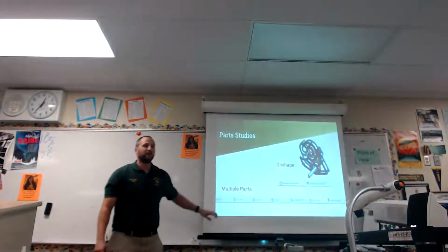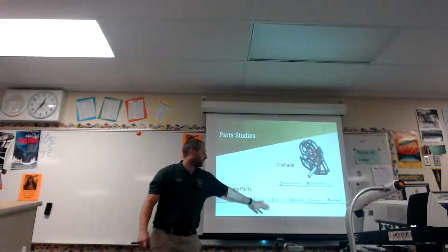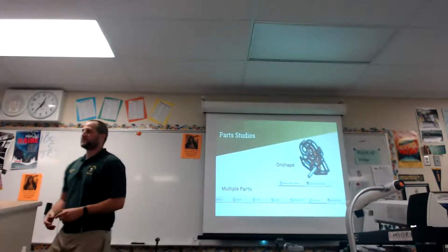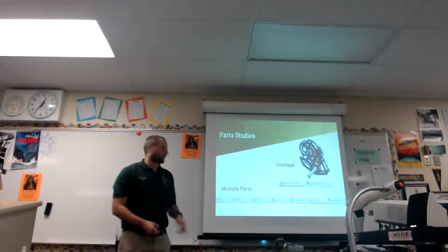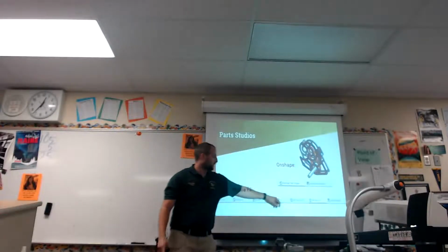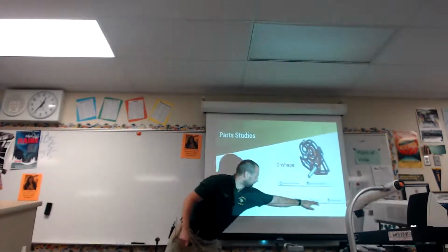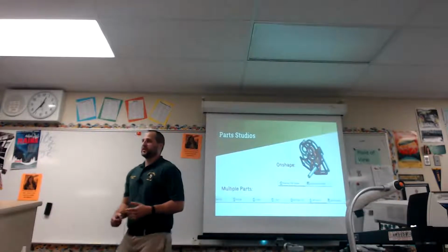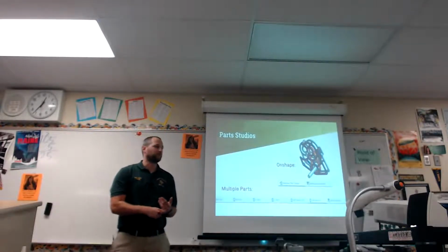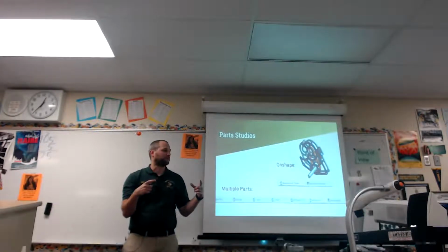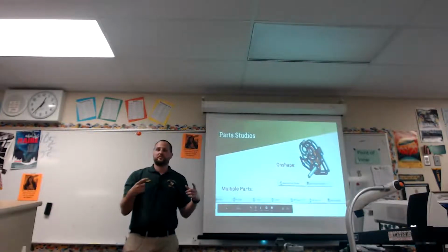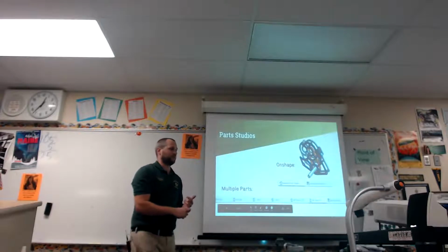All right. So one of the things that's unique or cool about Onshape is along the bottom, you see kind of your standard workflow that you'll have in different CAD packages. You build all your separate parts, and then you come down and you assemble them. And Onshape uses something called part studios. You still end up with unique separate parts, but you build them in one big container file called a studio. And that gives you some advantages as far as parts that relate to each other.